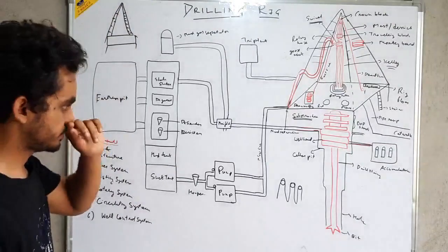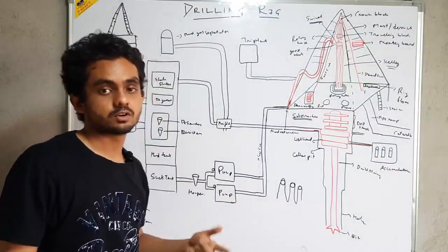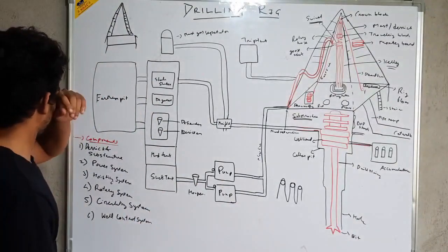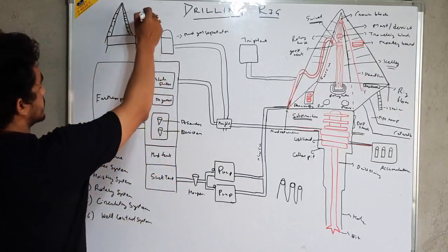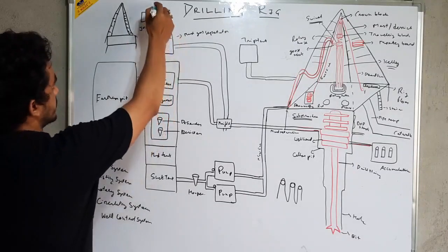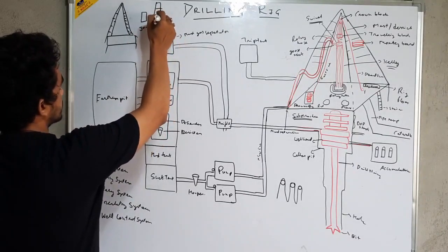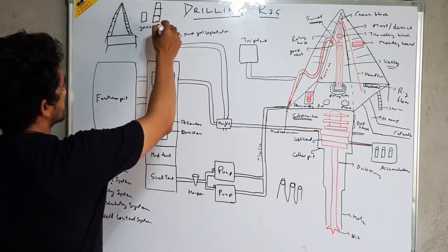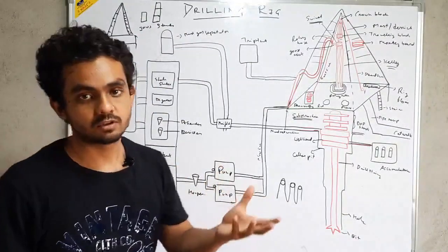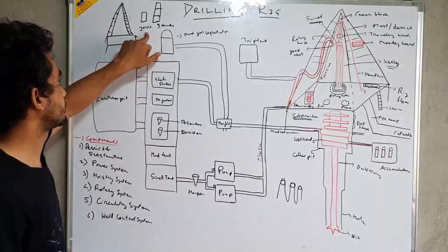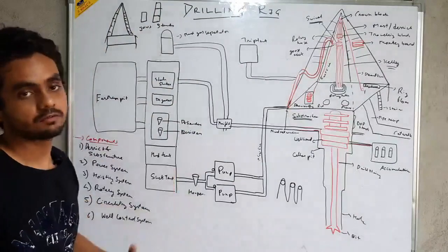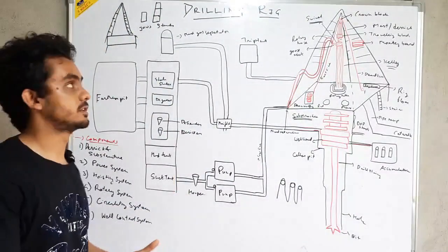Why is it important to provide the necessary height? As you might have come across somewhere, drilling is done in joints. A joint means a single drill pipe. But tripping out is done in stands. One stand equals 3 joints. So a stand is a combination of 3 joints. One joint basically has a length of 30 feet, and a stand will have a minimum length of 90 feet, if we consider the general configurations.